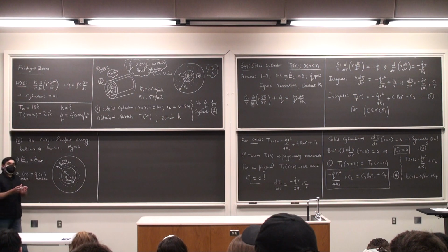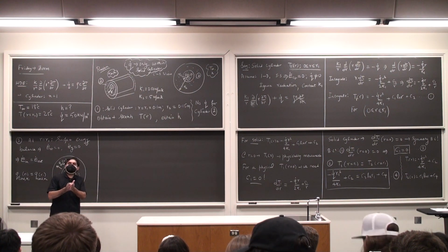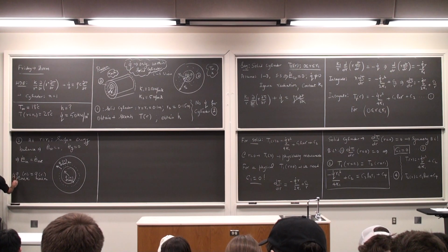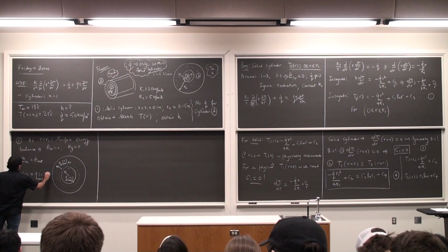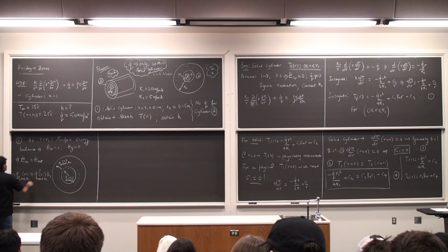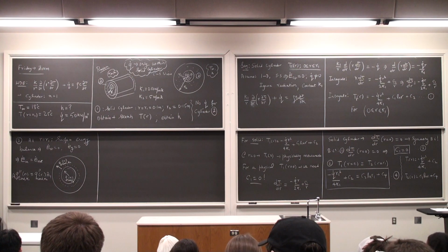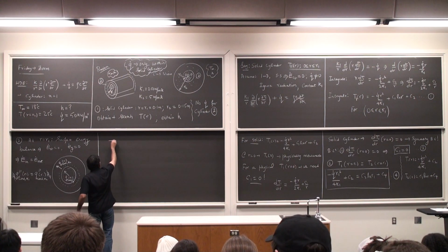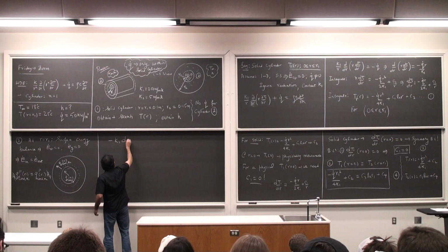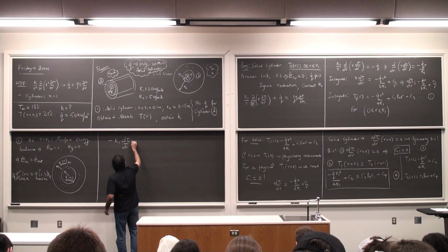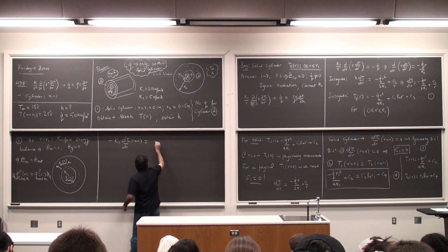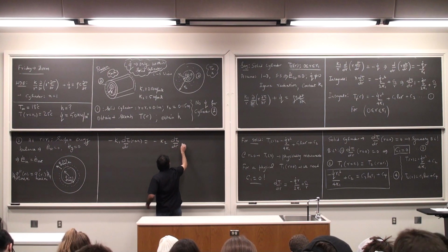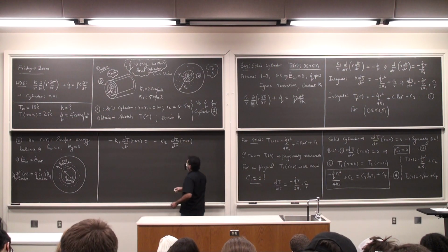The area of heat transfer is the same because I'm at the same interface, so I can essentially say that this is the flux. So if you want, you can call it A at R1. Write these as the flux, watts per meter square, cancel off the areas, and so I have the following. Minus K1 dT1 by dr at R equals R1 is minus K2 dT2 by dr at R equals R1.